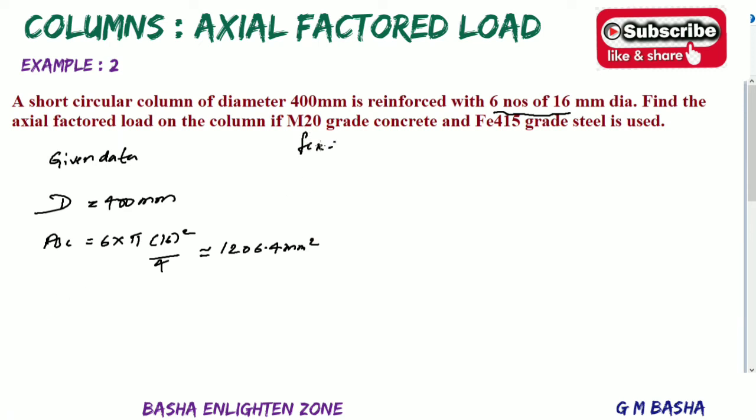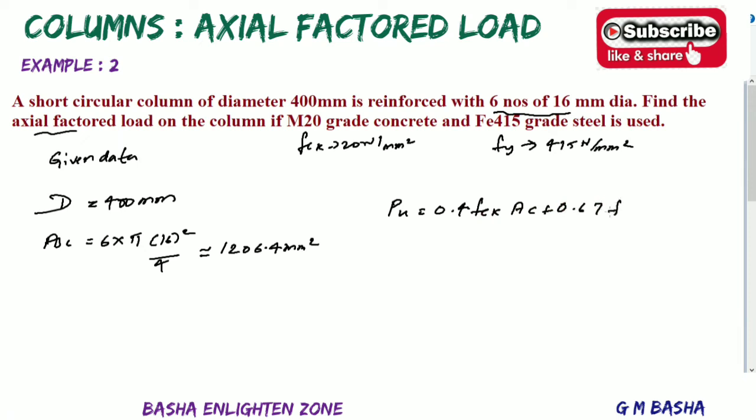Then the requirements: fck is 20 Newton per mm square and fy is 415 Newton per mm square. Then find the axial factored load. We already know the formula: just substitute Pu equal to 0.4 fck Ac plus 0.67 fy Asc.